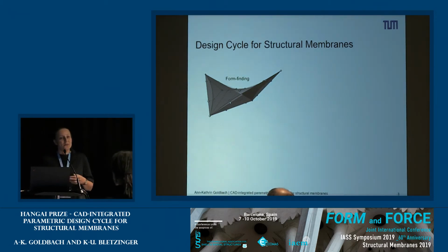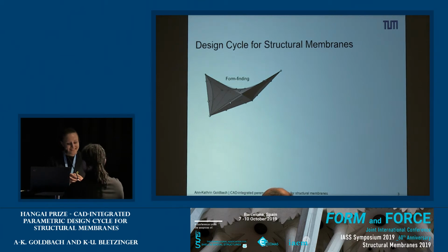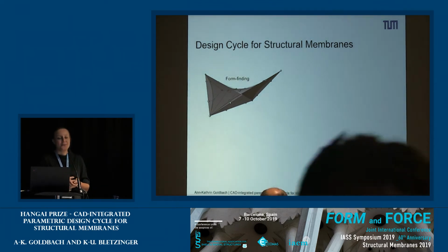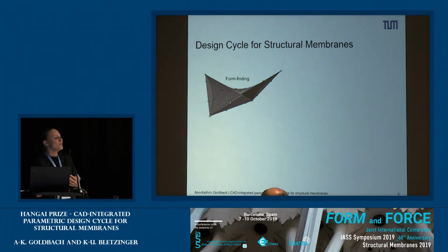And then we have an idea of the pre-stress setting we would like to achieve, and can implement all that into a starting geometry, perform a form finding procedure, and then get an equilibrium shape that satisfies both the pre-stress conditions that we set and the boundary conditions.